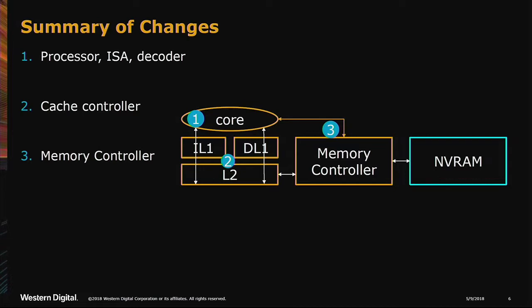Additionally, the memory controller. If we want our RISC-V processor to be able to write directly to memory to bypass the cache hierarchy, then it needs some kind of memory controller or something in hardware somewhere to allow that to happen. Could be via a write combining buffer or what have you, but this functionality would be necessary as well.